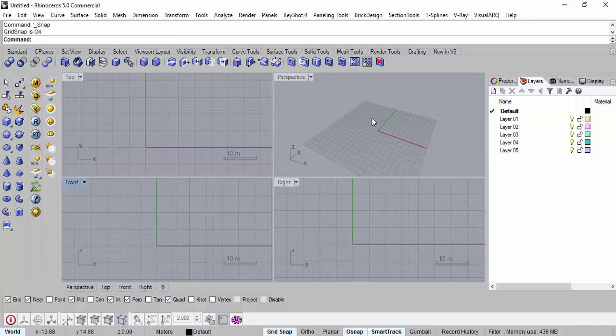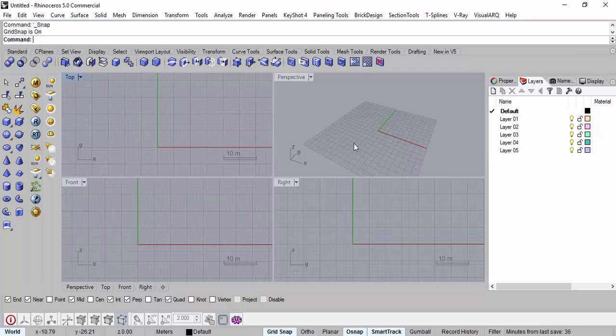Don't ever assume that this is flipped or something. Just because you need to draw in front view, you need to have the 2 dimensions, X and Y. So likewise I can set these construction planes in any way. I mean, it doesn't have to be only horizontal or vertical. I can make an inclined plane like that, right? You see my hand is inclined. I can put a plane on it and I can start drawing on it. So I will still have my X and Y. Are you getting it? So that's the difference between world and construction plane.